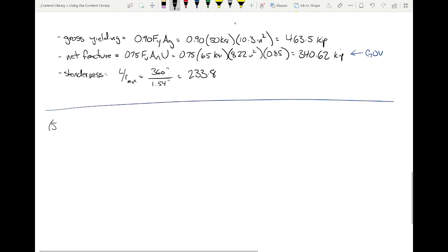So I want to summarize. Pu was 332 kips. Again, we're actually putting 240 on it, but I'm designing it for 332. Its usable capacity is this. Even though it can probably hold up more in the real world, I am bumping it down a little bit, again, for safety, for the uncertainty. Now, is this member good? It is. Now, how can we express that numerically?